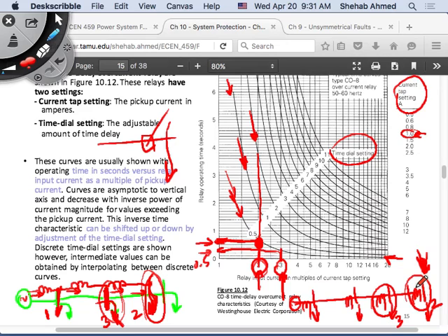But this is lower fault current than this one is set to disconnect at. This is set to disconnect at 3 amps very quickly. This one is set to disconnect at 2 amps very quickly, right? But if the fault current is 2 amps, meaning the fault is at the end, and this breaker does not work, the relay does not work, something happens, this is not functioning, I want to make sure that this backs it up. Well, what is the fault current?